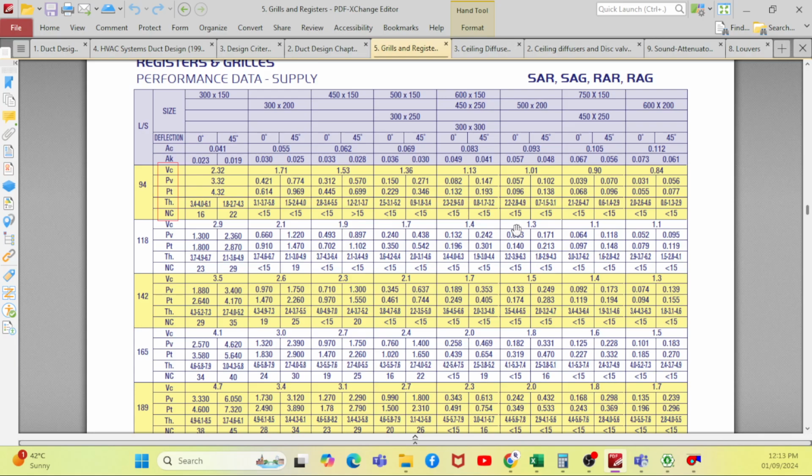That will not fit in your space. You are consuming larger space. Then the weight of the equipment will increase, and that will affect your structure. So there are many factors. If you go to any FCU catalog, normally they choose starting from 50 Pascal. In the worst case, you can go with the high static pressure.